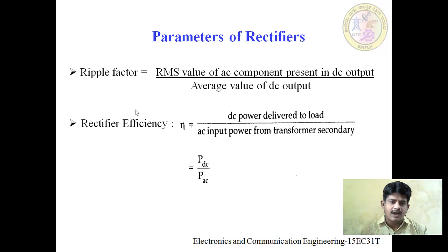And also we have an RMS value. What is meant by RMS value? Actually, it is the heating ability of the element. For example, if a DC value heats an element to a certain temperature, the equivalent AC value that produces the same heating is considered the RMS value. RMS means root mean square value. Similarly, average value is about transferring charge.